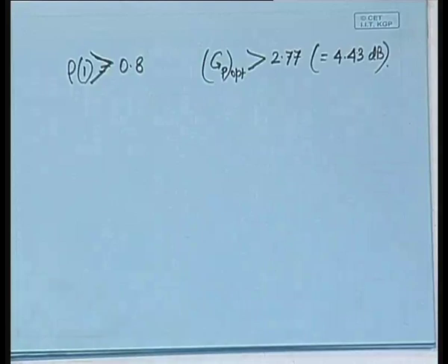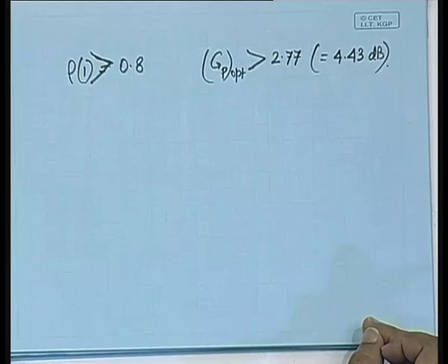That is of course a hypothetical case, but for all practical purposes we will have rho 1 in the range of 0.8, 0.9, 0.95. With better correlation, intuitively we gain further by utilizing the differential mode, because the differential signal variance would be much lower, and that would boost up the GP, the gain that we are obtaining.